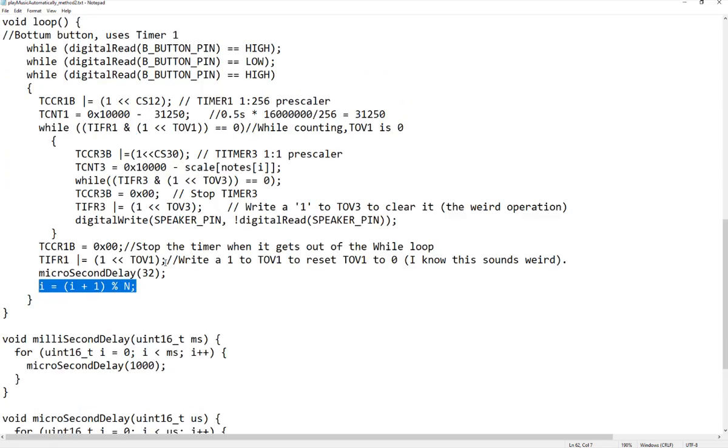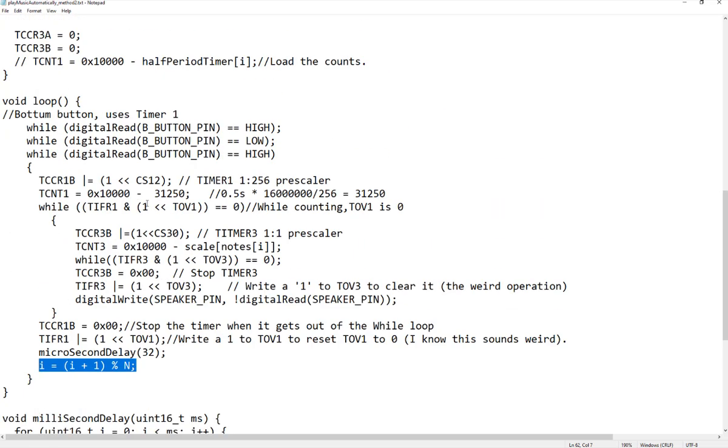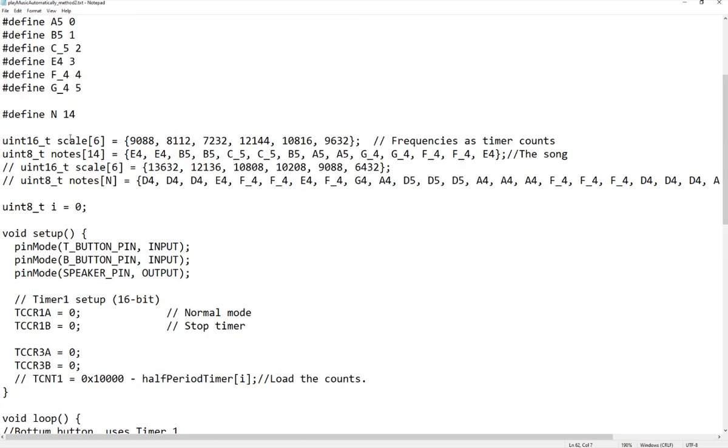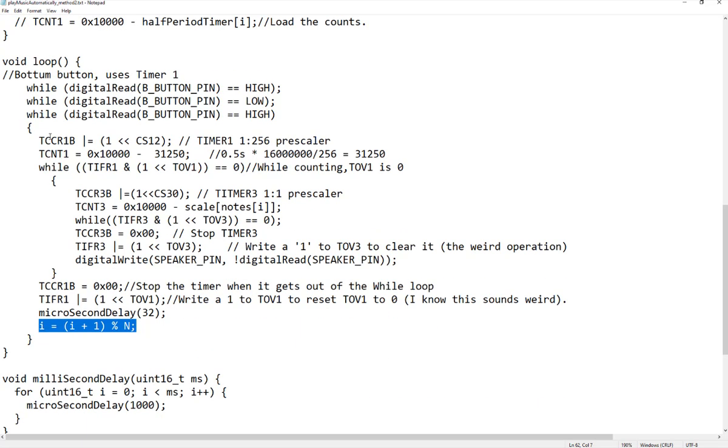That's it. So this one just uses a nested while loop to play it, but to control that, it could become super complicated if you have more stuff in there to be covered. So it's better to use ISRs in the future. That's why after this tutorial, we started handling the same thing. You can see the results are the same, but it's being handled in a way nicer way using ISRs instead of using nested while loops. Imagine you have like 100 nested while loops in the future.